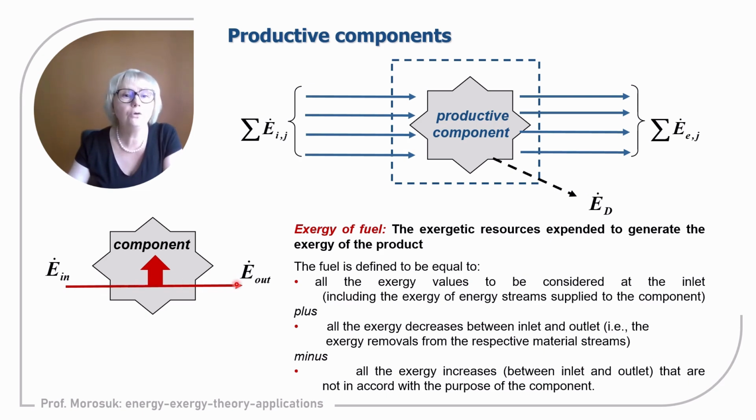If for this stream the exergy at inlet is higher than the exergy at outlet, it means that exergy is moving from this stream to other streams within the component. So this stream supplies exergy to other streams. It means that this stream is assigned to be fuel.